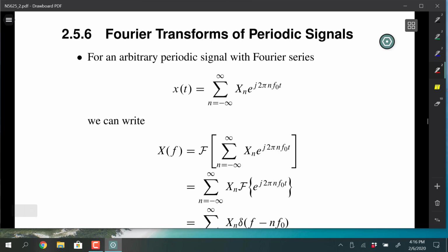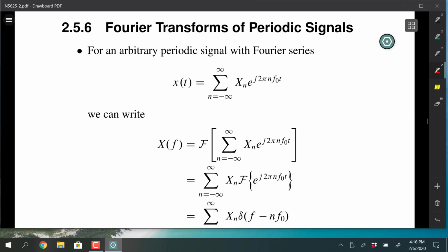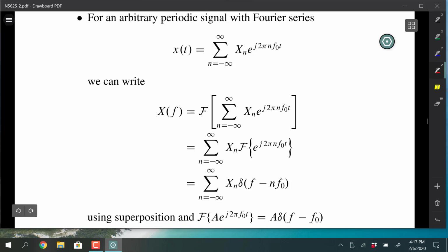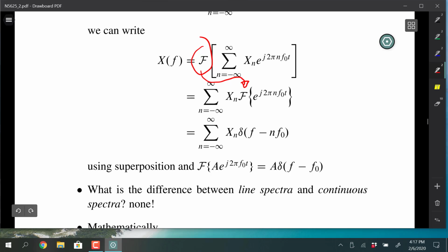So now we can consider the Fourier transform of periodic signals. So take the Fourier series representation for a signal and then go ahead and Fourier transform that term, but this is going to allow the Fourier transform and the limit idea to operate, so we're going to move it inside that doubly infinite sum, and each one of those complex sinusoids becomes a frequency shifted delta.